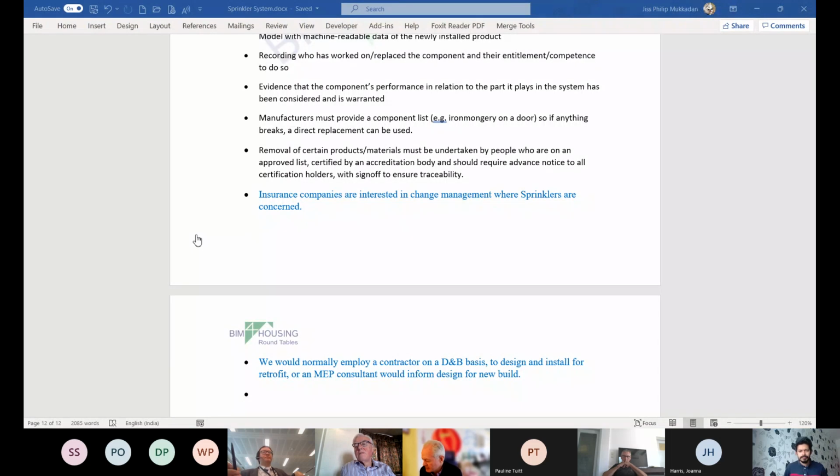One thing I can tell you is that if you have sprinklers in a flat, you can have an open plan flat, and without them you can't. And I guess as more and more people now know that most flats are going to need sprinklers, you can take that into account from the beginning. But I can imagine on a lot of projects this was not realised, and so that could be what you're describing: they'd laid out the flat in a certain way, where you come in your front door, you've got your corridor, and every other door leads off that into other rooms. Yes.